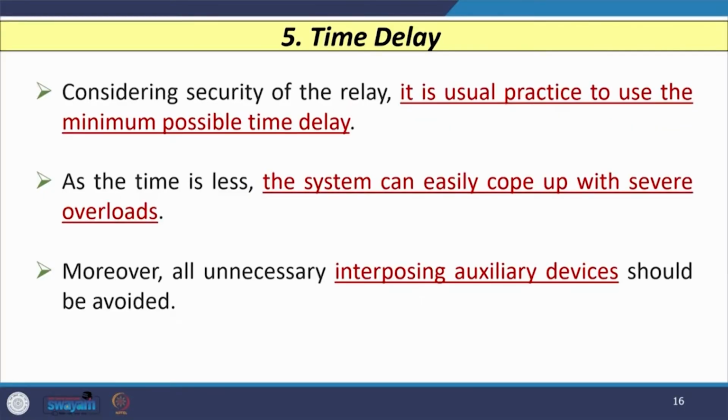Now, the fifth factor which is going to affect the design of an intelligent load shedding technique is the time delay. It is the usual practice to use the minimum possible time delay. When the time is less, the system can easily cope with severe overloads, and all necessary interposing auxiliary devices should be avoided. However, one important condition is that time delay is needed only during specific situations.